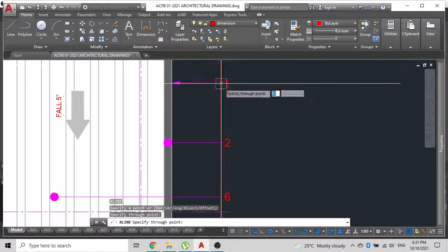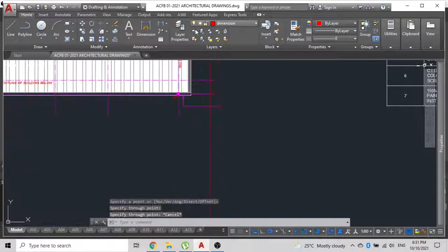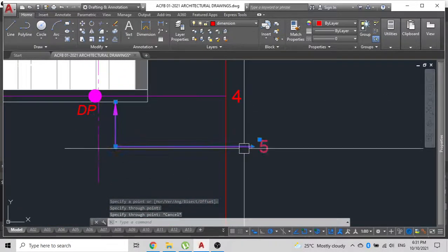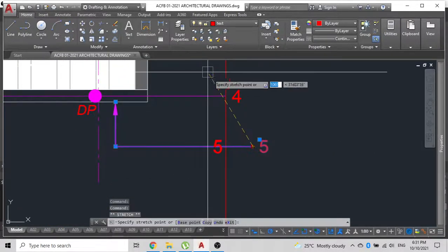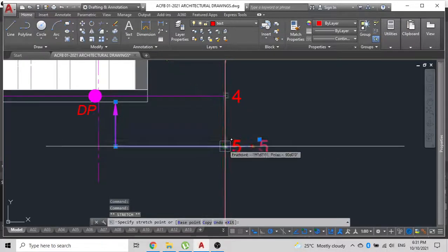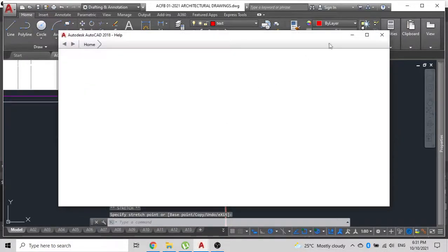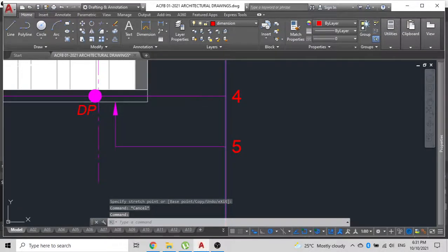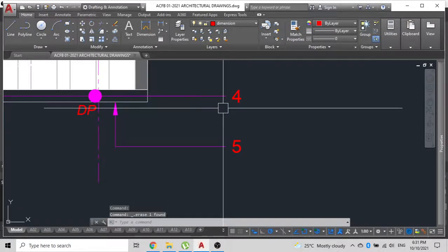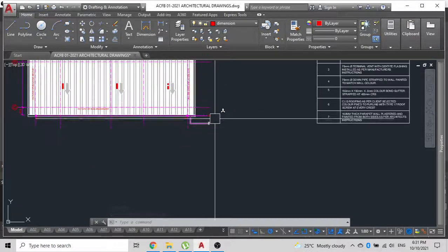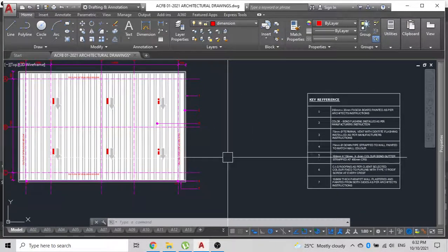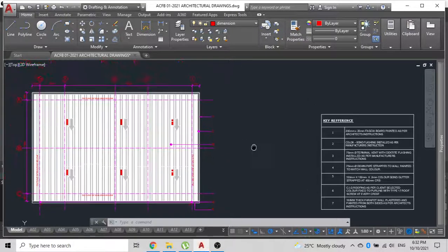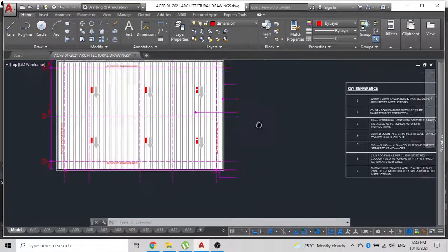So what you can do is draw a construction line and just bring the ones that are out of line into place. In this case, it's leader number 5. I'll bring them there like so, or you can also bring it here like so. Now while drafting, you also have to be careful what keys you press. If you press F1 instead of escape, you will get a help window. This tends to become a bit annoying, but you have to deal with it.